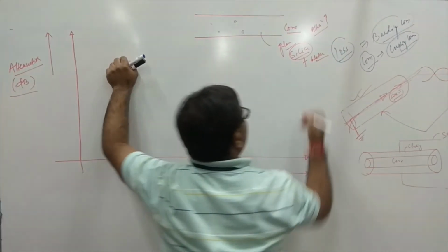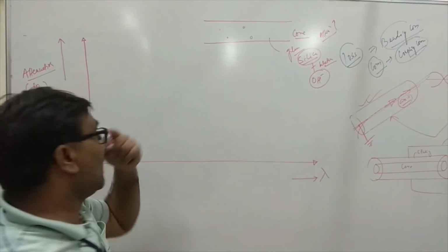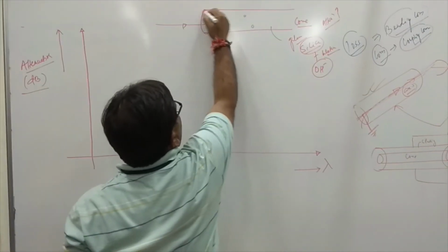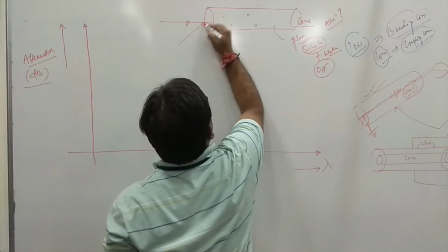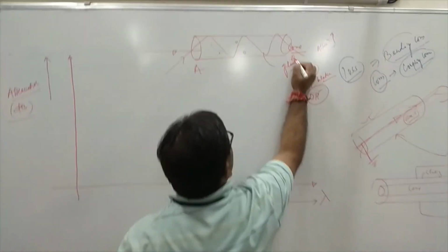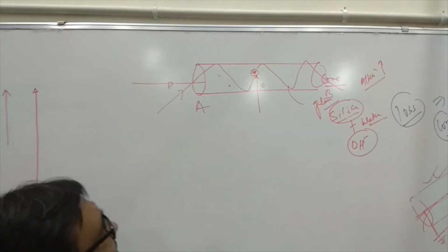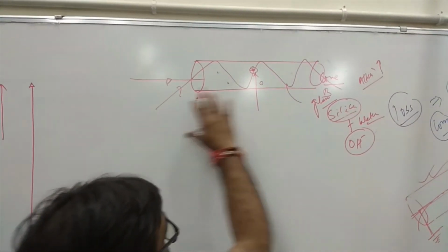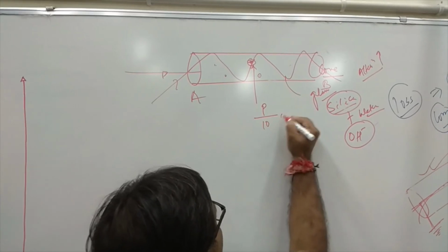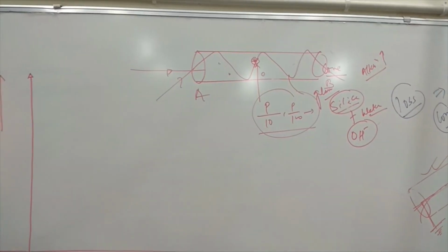Water molecules also constitute OH minus ions. Now light enters this glass at some angle and, through TIR, travels from A to B. During this journey, let us assume that this impurity has an impact on the light. Due to these impurities, the power can be reduced by some factor.